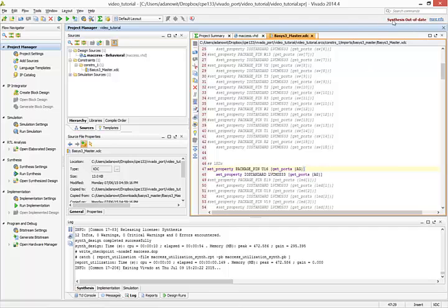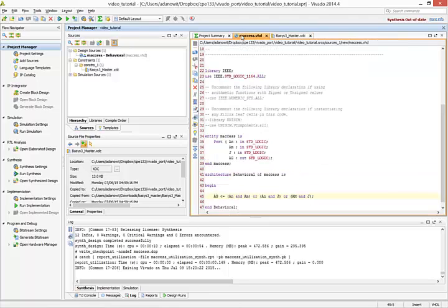You'll notice up here it says synthesis is now out of date, because Vivado uses the constraints files in the synthesis. Now that we've modified the constraints by adding some constraints, we have to resynthesize the design. But before we do that, we're also going to set something else in what are called bitstream settings.